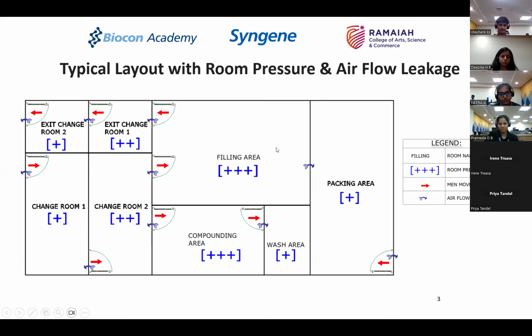If you see here, the filling area, my supply air volume was 2000. Correct? When I am supplying 2000, my exfiltration going out of these two doors was 50-50, and my exfiltration going out of this opening was 100 CFM. Thereby, my return air from the filling area has reduced to 1800.